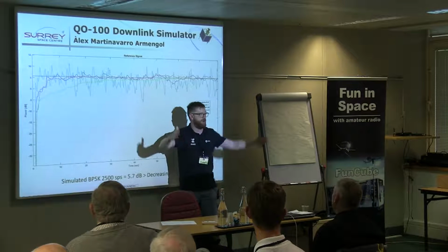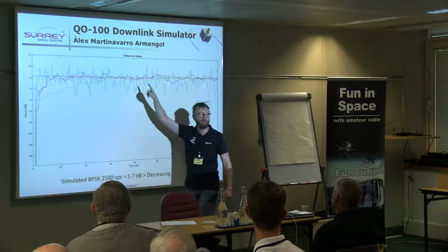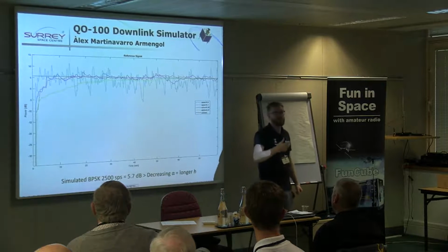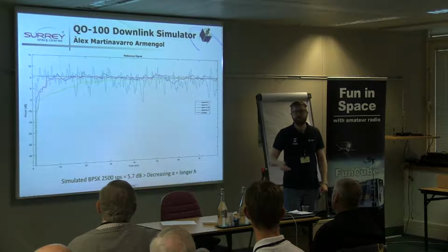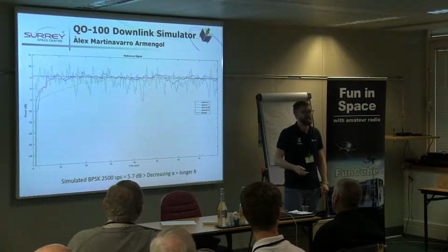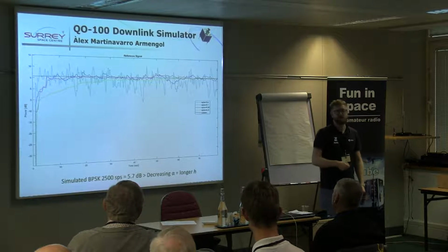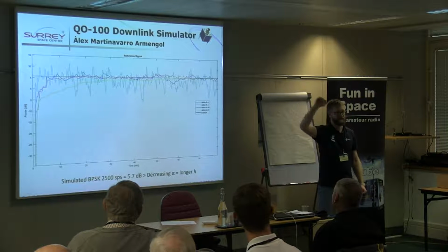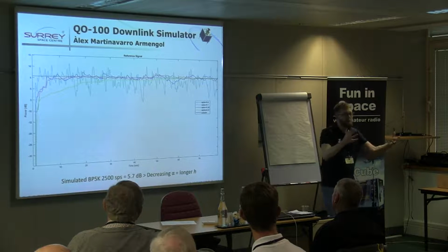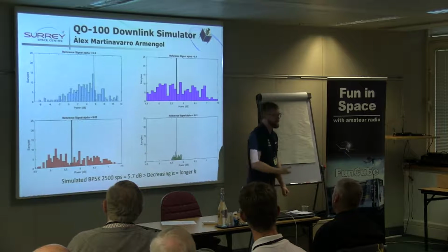And of course, if you then over-constrain it and over-filter it, it just takes longer to go up. So you can see this as almost an integration time type of problem. You need a certain number of samples to be able to effectively make your calculation within a certain level of statistical confidence. The question is do you want loads of samples quicker, or do you want to do it steadier and get to that point slower? By the by, these mean the same thing. But you can look at this in a couple of different ways and do the statistical analysis.